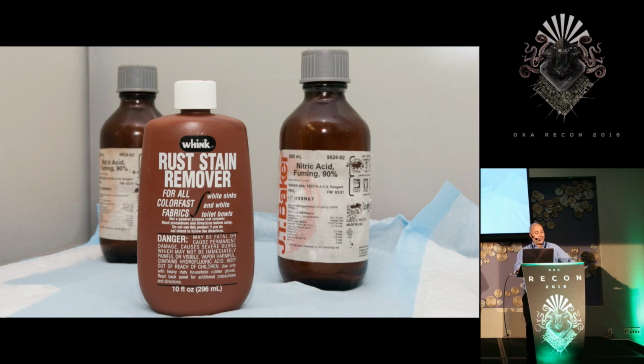To delayer the chip, I use hydrofluoric acid to perform a wet etch. I use the Wink rust stain remover product. It's available in hardware stores all over the USA. It's a dilute HF solution that works really well for delayering ICs. Put a small amount of Wink liquid in a beaker, heat it on a hot plate, drop the decapsulated die in. Using a pipette, I agitate the liquid to disturb the bubbles that form on the surface of the chip, and then the acid etches the chip more evenly. You probably don't want to breathe in these fumes, so do this in your garage also, in your fume hood.